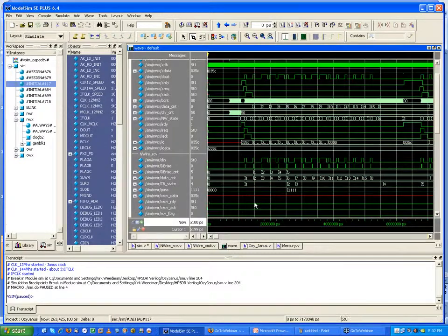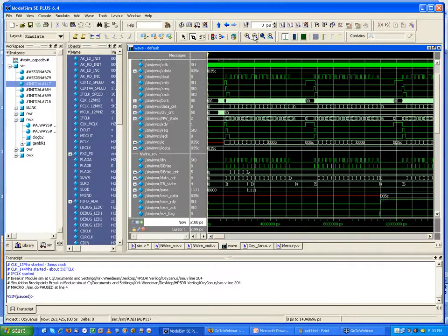Right here in this simulation, you see that the receiver starts off, and this thing called pass in the receiver is what determines that it has figured out how to sync to the data, so all these 4 bits go high. But it started off running at the same time as this one, so it didn't have any trouble. It could figure it out real quick, so on the second data stream it could grab the data and knew enough about the width of all these bits to grab the data properly, and sure enough it did, the 35C that I sent out from up here. So it only took one stream to get it.